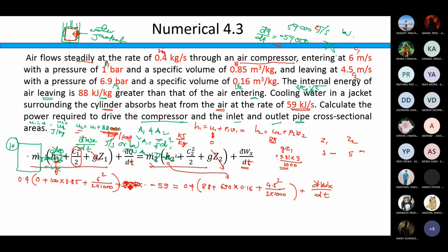Now, without solving this, I would say your answer will be negative because this is an air compressor, a power consuming device, right? So work is done on the system. So you will get the minus sign for the value. If you are not getting your minus sign, it means something is wrong with the data itself.